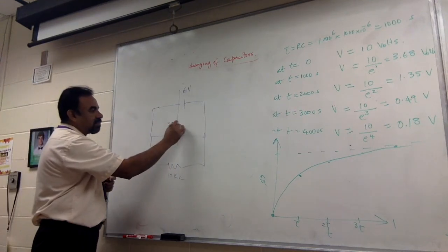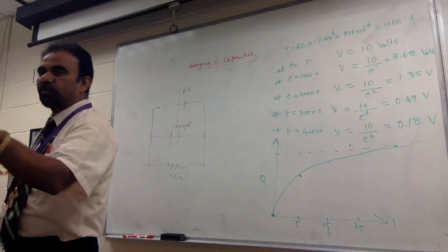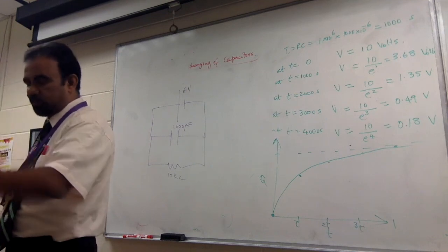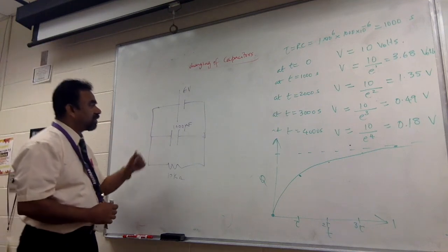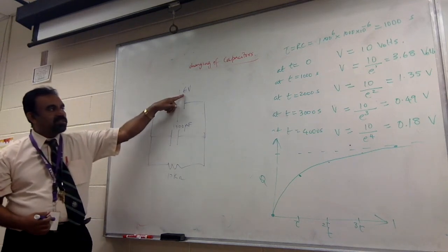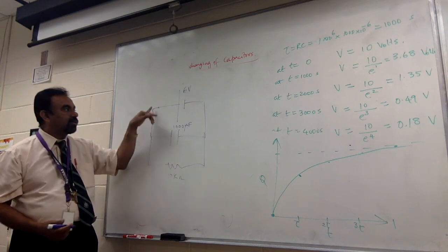And this one is 1000 microfarads. It's 1000 microfarads, but very small because it's only capable of handling 16 volts. But I'm not going to put too many volts into this, so that should be good enough. So I'm going to connect this up, and when I connect it, the 6 volts will go straight up here, right? And then I disconnect it.